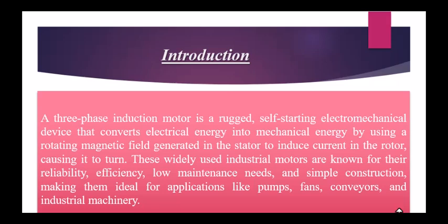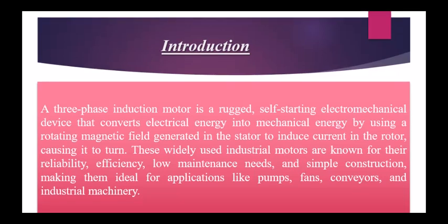The motor basically converts electrical energy into mechanical energy by a rotating magnetic field in the stator. In the induction motor, there is a stator and the rotor. On the stator, there is a magnetic field called the stator magnetic field, and on the rotor, there is a magnetic field called the rotor magnetic field. The speed of the rotor magnetic field is slightly less than the stator magnetic field, which produces torque in the motor, due to which the induction motor runs.